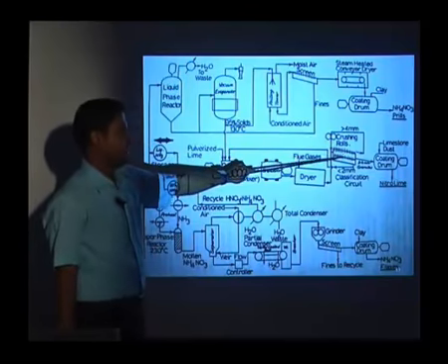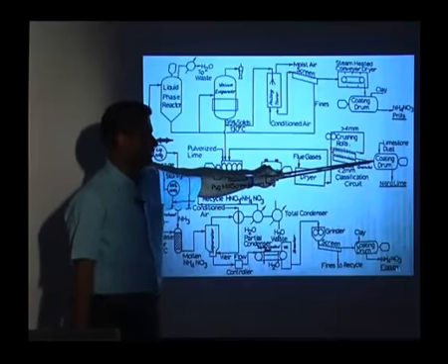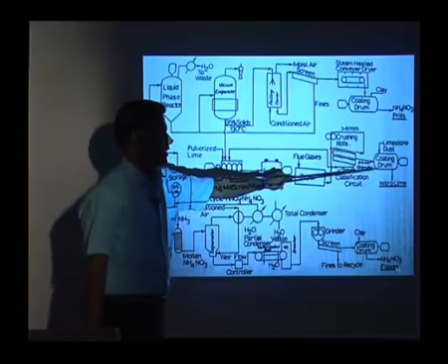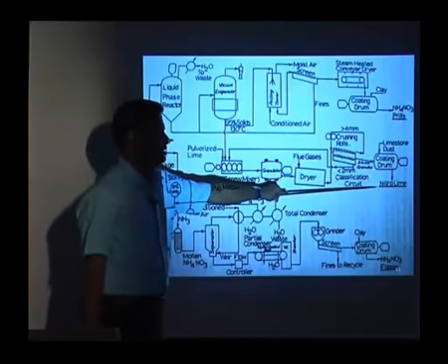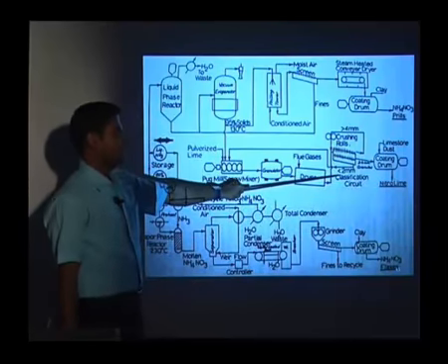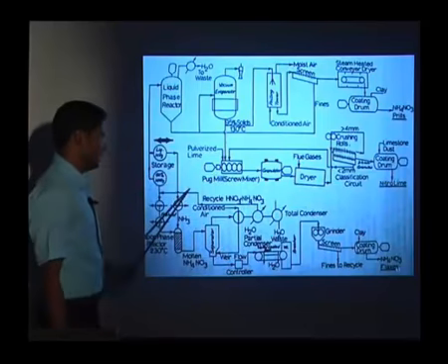and when we get the desired size of 2 to 4 mm granules, then we send them to the coating drum. Then with the limestone dust, we can have the coating over them and we can send them out as nitrolime. And the particles which are less than 2 mm, we can send to the classification circuit.